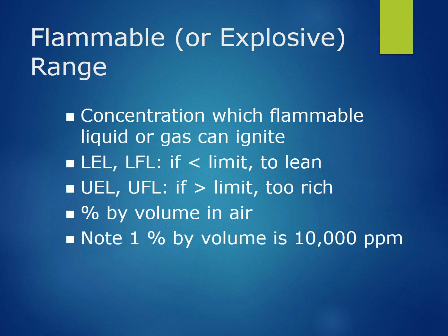The flammable or explosive range of chemicals is also very important. We not only use this for flammable liquid storage and fire prevention, we also use this in confined space entry. Chemicals have calculated values at which there has to be enough vapor in the air to support combustion.